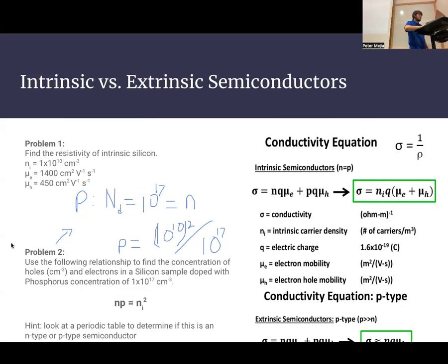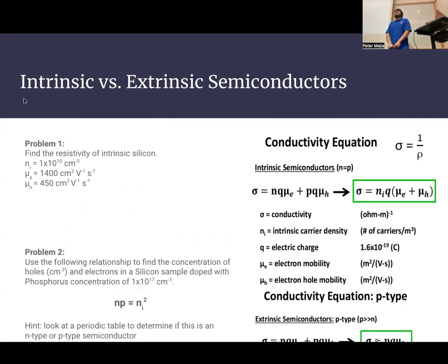But the material to the right of silicon would be 2 times that, right? Would you have double the donors? If it's sulfur, I don't know if that's used. Sulfur doping. If you have something to the left over by 2 from silicon, like barium or something, would that be 2 times the concentration, the number of electrons donated? Because now it's 2, I get it, but I've never seen that. That's a tough one. For actual manufacturing of that, it's close to impossible.